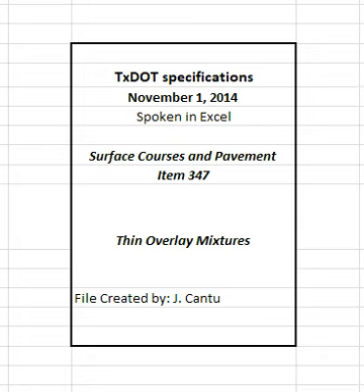4.3.4 Loading and transporting. For loading and transporting, include type and application method for release agents, and truck loading procedures to avoid segregation. 4.3.5 Placement and compaction. For placement and compaction, include proposed agenda for mandatory pre-paving meeting, including date and location.